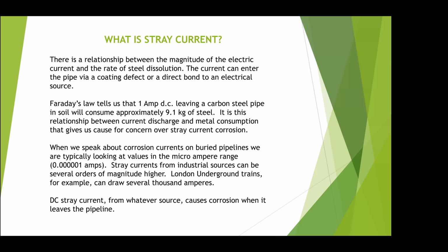But DC stray currents are a major problem for us now in pipelines because, well, it's always been well known, but it's becoming more prevalent now because of the energy corridors we use, particularly in this country, where land is not so abundant, we don't have a lot of real estate, so they tend to put the pipes and the overhead power lines in the same corridor.